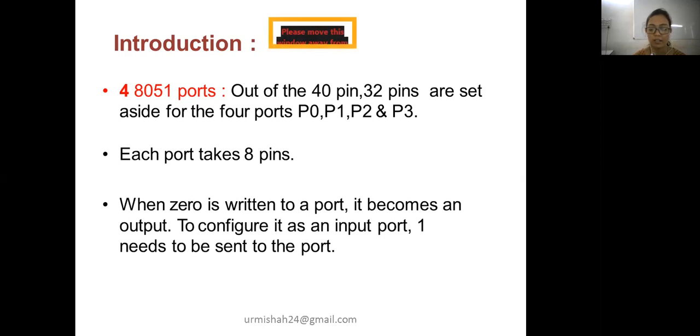Now, these ports can be treated as input port as well as output port. How can you consider whether your port is treated as an input port or output port? Input port means, if you want to read any data from your input output peripheral, then you have to treat your port as input port.